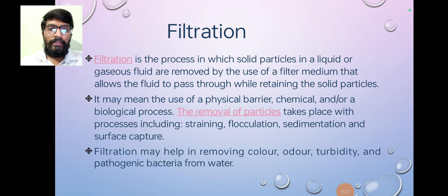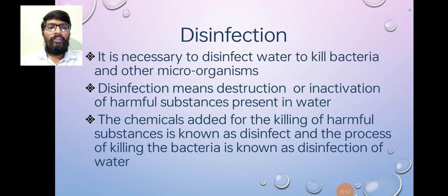The filter media uses physical barriers and chemical and biological processes. Particle removal takes place through straining, flocculation, sedimentation and surface capture. Filtration helps in removing color, odor, turbidity and pathogenic bacteria from the water.